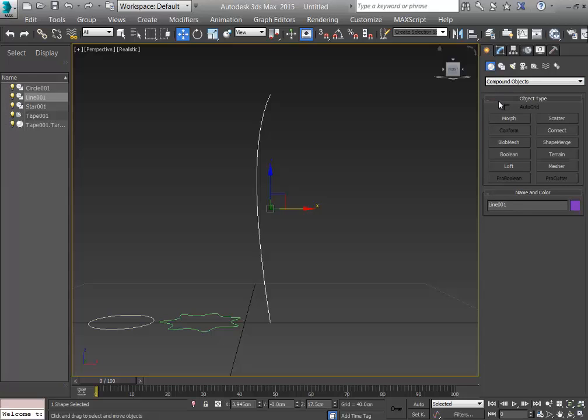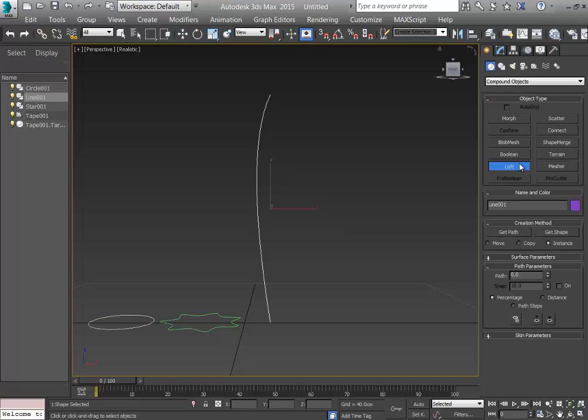So in the compound objects, I have a tool named LOFT. Now it is ready to be a vase. While the LOFT tool is selected, I'm just checking where my LOFT tool starts. It's saying that now it is at 0%. You can even see in terms of centimeters, because we know that the whole vase is 35 centimeters. You can define it by centimeter scaling as well. But I'm just happy with the percentage for this level, for the first level.